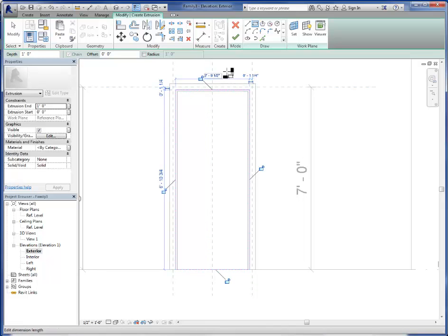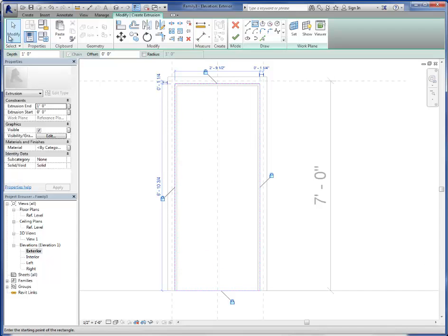And so then it's going to automatically try and snap to some of these things, and we want to go ahead and lock those relationships because we want the door to essentially maintain its width in relation to all of that, the door jamb and door stop. So we'll go ahead and lock those connections.